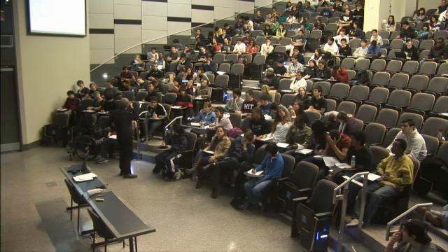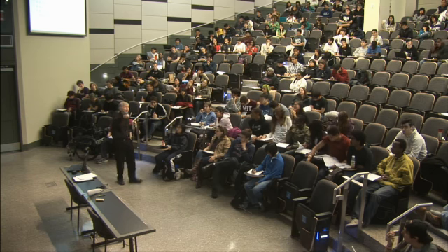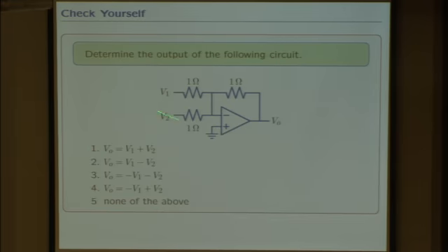That's hard, huh? Well, I've got a union here into which 3 different currents can flow. How big is the current that can come into this node? What's the sum of all the currents that can come into that node? Well, one could come in this way, one could come in that way, one could come in that way. How much current flows in the minus lead of the op-amp? None. No current goes into the minus. No current enters the op-amp through the minus lead.